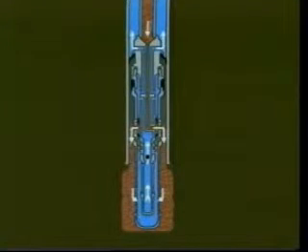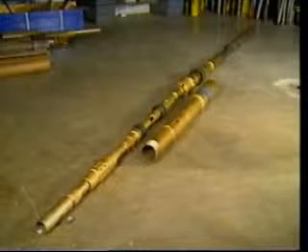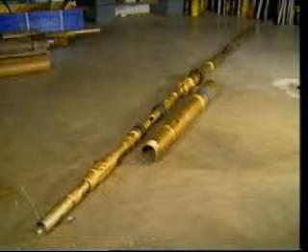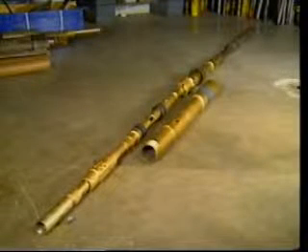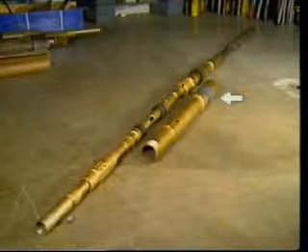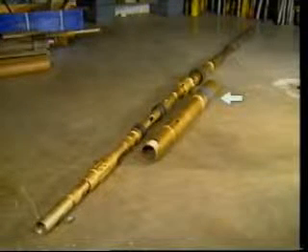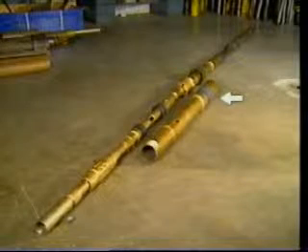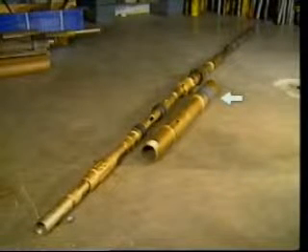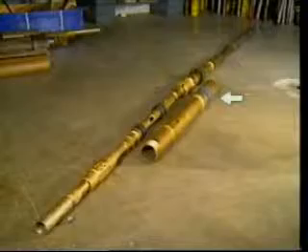Like the cased-hole gravel pack, this system allows the implementation of a circulating gravel pack around a slotted liner or screen. One advantage of this particular tool assembly is that the gravel pack operation can be performed with a lead seal adapter in place on the assembly, thus eliminating the need for an extra trip to install the lead seal assembly. This assembly is also run on a work string.